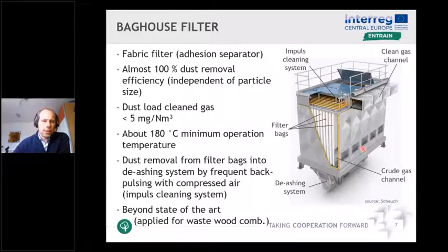About 180 degrees Celsius minimum operation temperature of the flue gas is needed here, so even a bit higher than for ESPs. And for baghouse filters, the dust removal from the filter bags is done by an impulse cleaning system. You can see on the top here.